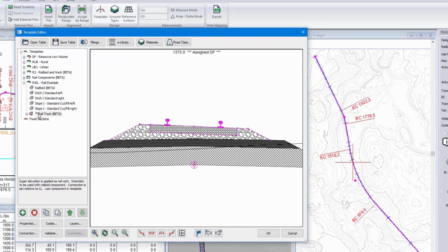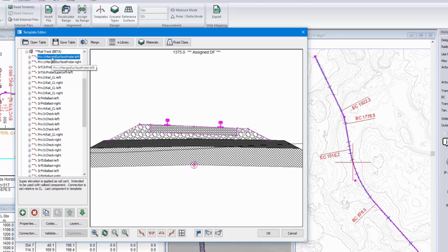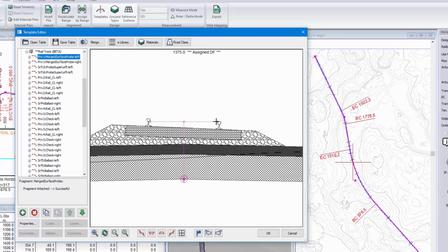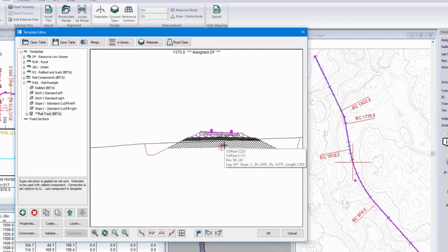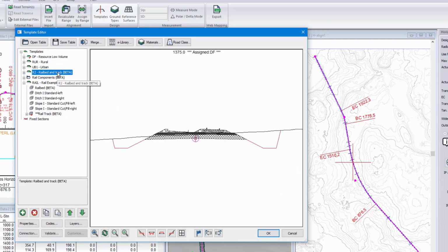And just for a quick graphic, so it doesn't have a need to go in here, but we can see that's benchmarked there, and that is raised from that elevation. So that is the rail track and rail bed component. And just a last quick note, you can apply several tracks to the same road bed and use offsets and change the point codes for displaying.